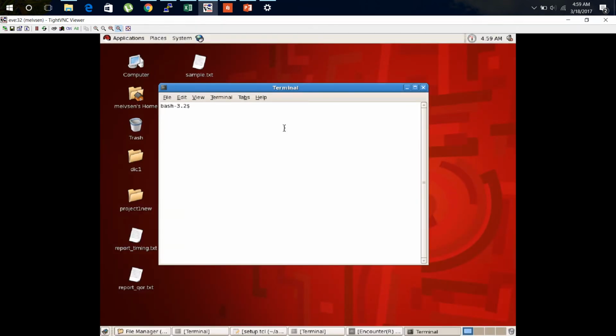So we'll start with DC, where we'll convert the RTL design of the 5.4 design, which is in SystemVerilog, into a netlist. I'll be doing the commands and explaining them as I run them. So first we'll open DC shell.